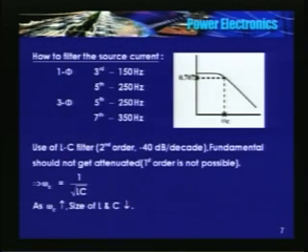But now, how do I reduce the harmonics? My application requires AC to DC power conversion, and the voltage has to be varied over a wide range. Suppose my DC motor has to be fed from a power electronic converter; the voltage has to vary over a wide range to vary the speed. So I have to introduce alpha, and harmonics will be there. What is the solution?